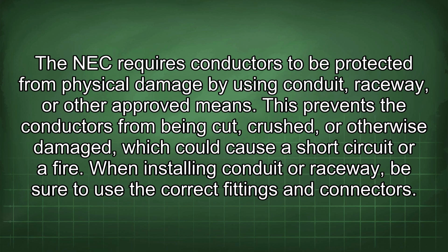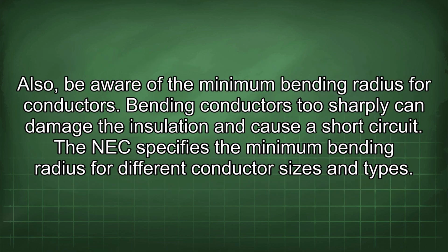When installing conduit or raceway, be sure to use the correct fittings and connectors. Also, be aware of the minimum bending radius for conductors. Bending conductors too sharply can damage the insulation and cause a short circuit. The NEC specifies the minimum bending radius for different conductor sizes and types.